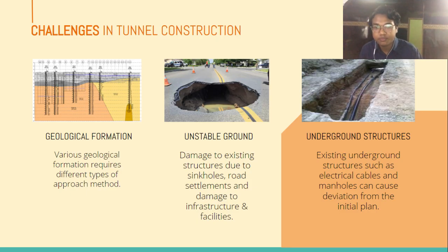Challenges in tunnel construction. Number 1 is geological formation. Various geological formations require different types of approach methods. For example, hard soil, soft soil, and hard rock or clay will require different methods of tunneling. And number 2 is unstable ground. Damage to existing structures due to sinkholes, road settlement, and damage to infrastructure and facilities. This is because the tunneling work that is happening underground can cause the ground to lose its integrity and fail.